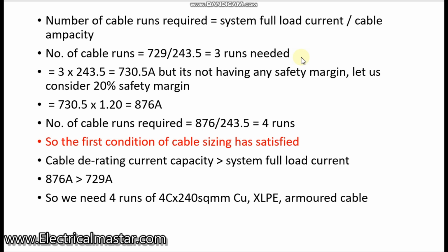If you do not consider the aging factor, there is a chance that during 10 years of continuous operation the cable insulation will fail. So you add a safety margin, 20% extra to the derating factors, then it will be sufficient to keep the cable for another 10 to 20 years without any aging issues.